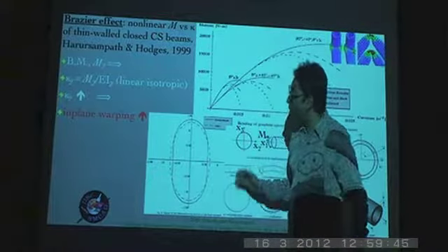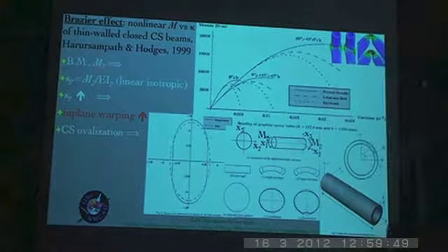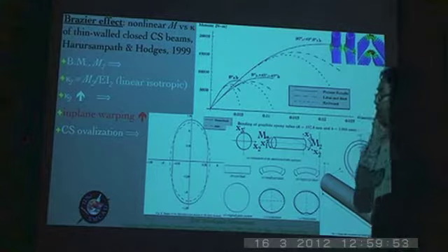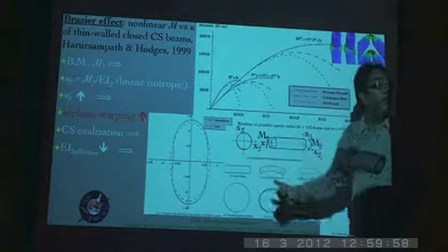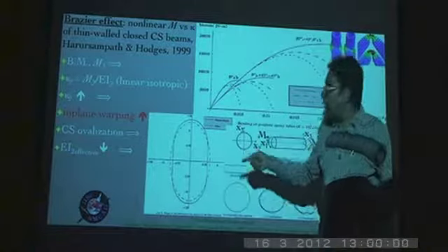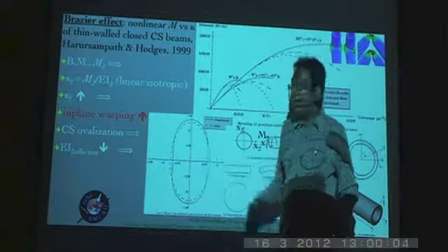So you have W2 and W3, in particular W3. There is a cross-sectional ovalization. It no longer is a circular cross-section; it's an oval type of cross-section. Because you can get closed form analytical solutions for your W2 and W3, you can actually get the geometric shape of the cross-section also as a correct result.